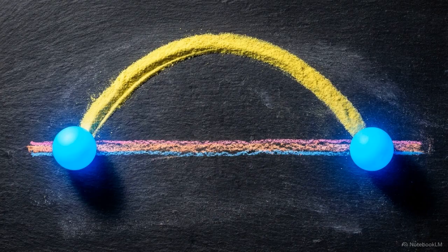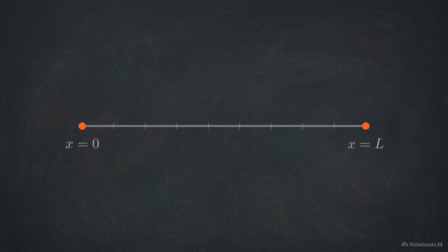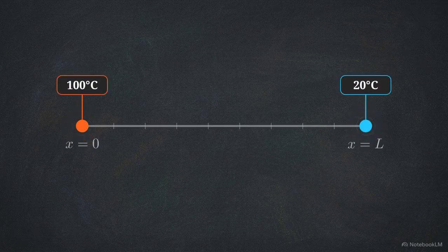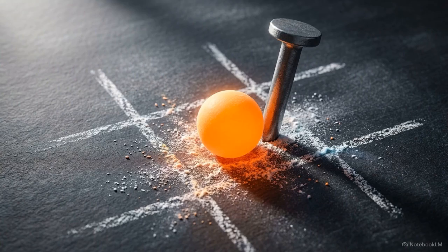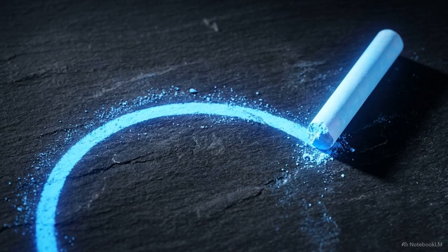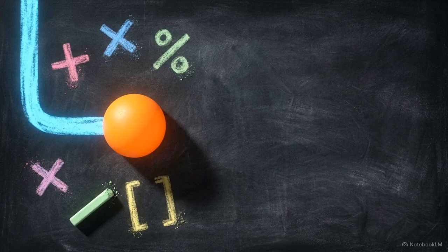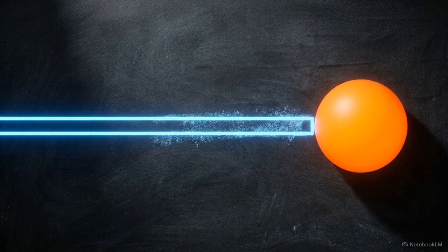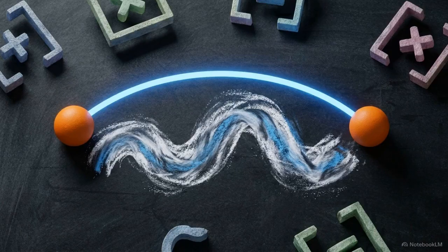The Galerkin method imposes a strict initial rule. Any trial function we design needs to satisfy only the essential boundary conditions. In a one-dimensional model with a single degree of freedom, an essential boundary condition is simply the known physical value exactly at the nodes on either end. These end values represent the only fixed data points we possess in the local system. Every subsequent calculation must align with these known quantities. Our objective now is to engineer a continuous function that perfectly locks into these fixed boundary values, regardless of how the material behaves in the middle.